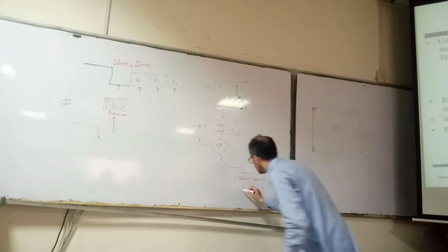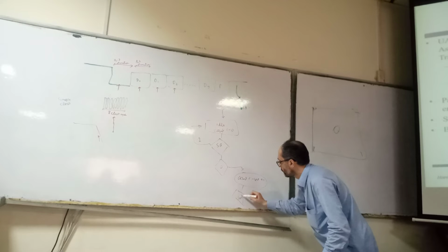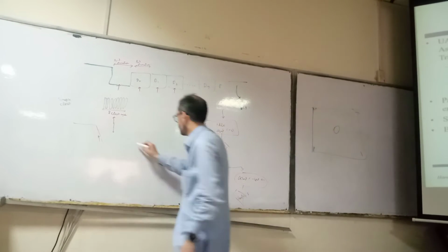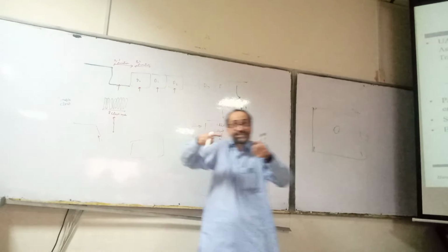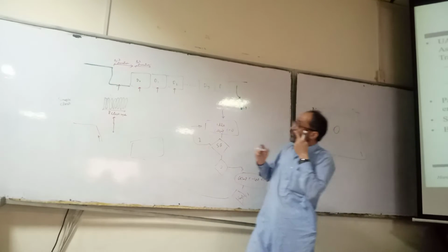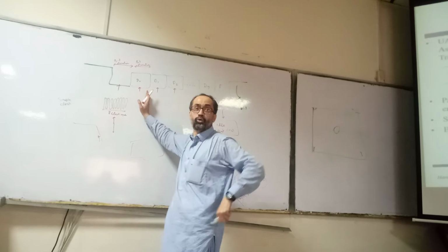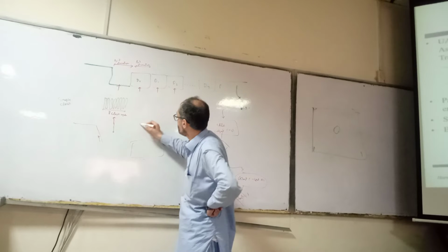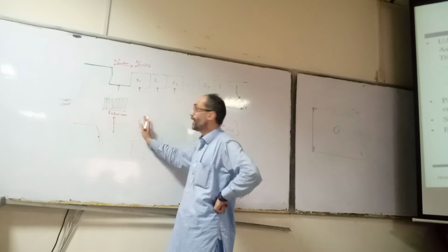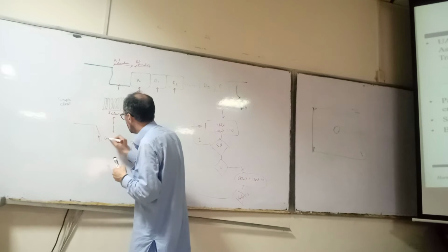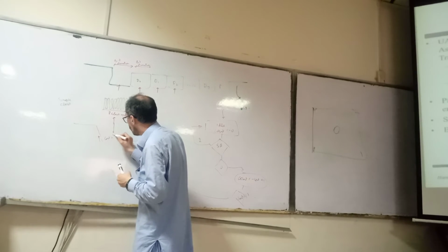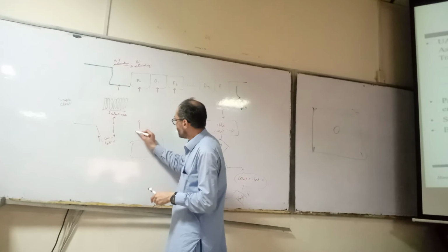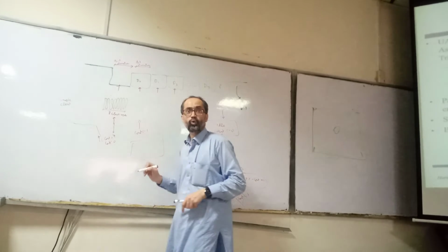Then you will check the count value. If count is equal to 3, then you will remove this start bit. Now, if we want to reach the middle of D0, how many clock cycles do we need? We need 8 clock cycles. And when count reaches 7, then we should reset the counter. And until this, bit count is equal to 1.